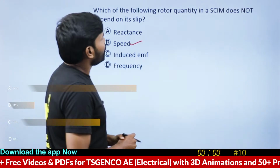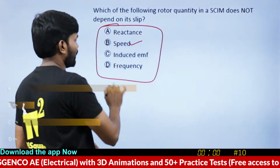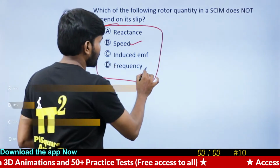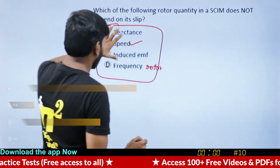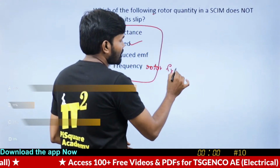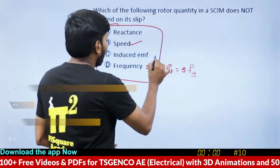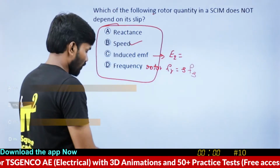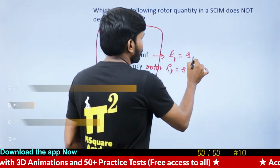Which are the following rotor quantities? So they're all rotor quantities. Frequency, don't think that it's a stator frequency, it's a rotor frequency, because it's not mentioned here, but it is said what are the following rotor quantities. Induced EMF, rotor induced EMF. So we know Fr is equal to S into Fs, right? And rotor induced EMF, or to be more precise, ER is equal to S into E2.